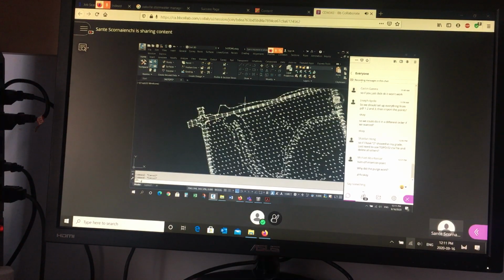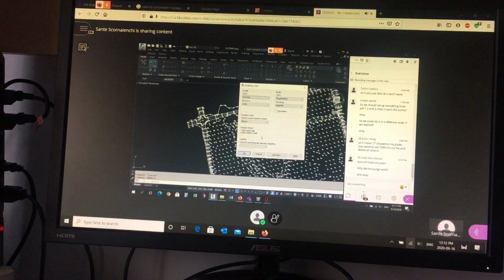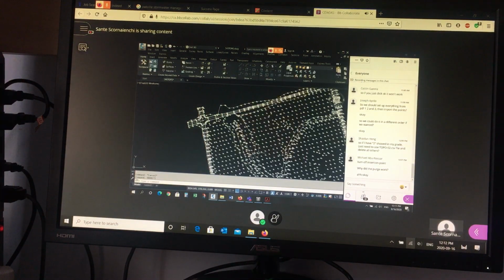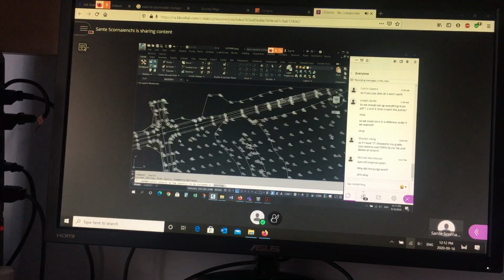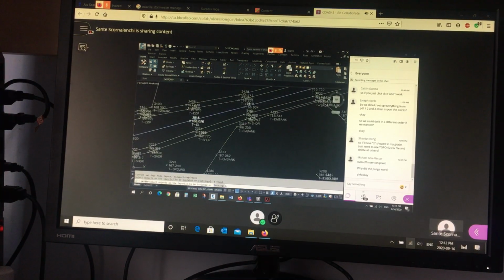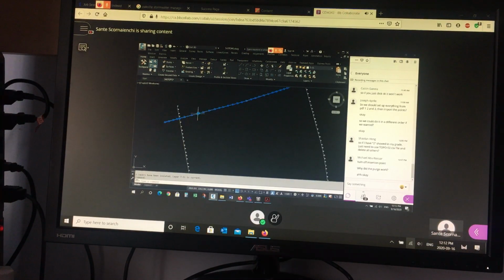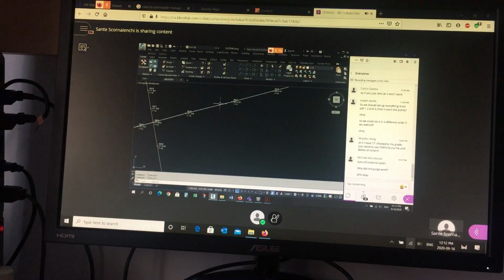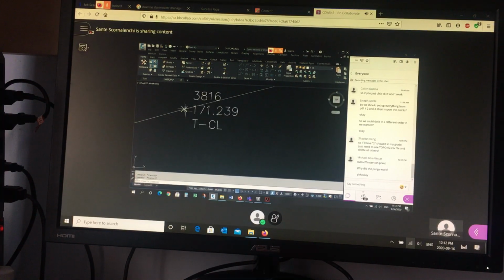So DD units, that's the command, DD units. Make sure this says meters. Open up the DXF and make sure that it also says meters. Save it and then come back and insert it here. Okay. So what you'll see now is a layer here, and that point layer here. Right? So now I've got all the dots connected. And you'll see the vertices of the polylines are exactly where the points are. It's just connected the dots.